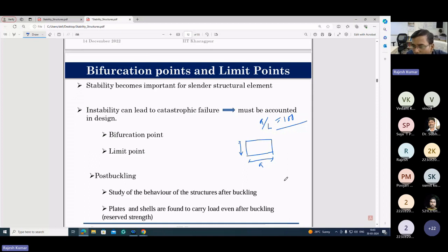And when you subject it to compressive loads, of any type, either parabolic or different types of non-uniform loads, coming from both sides, then this plate will deform abruptly. Out of plane deformations will take place. So this plate will go either inside or outside of this desktop. It means that it deforms out of plane due to the applied loads. This is known as buckling.